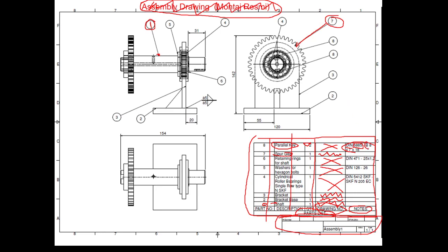And then the rest is for some technical notes after the code of the standard, after the ID number of the document. If we have some others, in most cases these are just, in brief, the main dimensions of such a standard object. For instance, it is 8 by 7 by 18. 8 by 7, just the size values at the cross section. 18 is the length of that machine element.